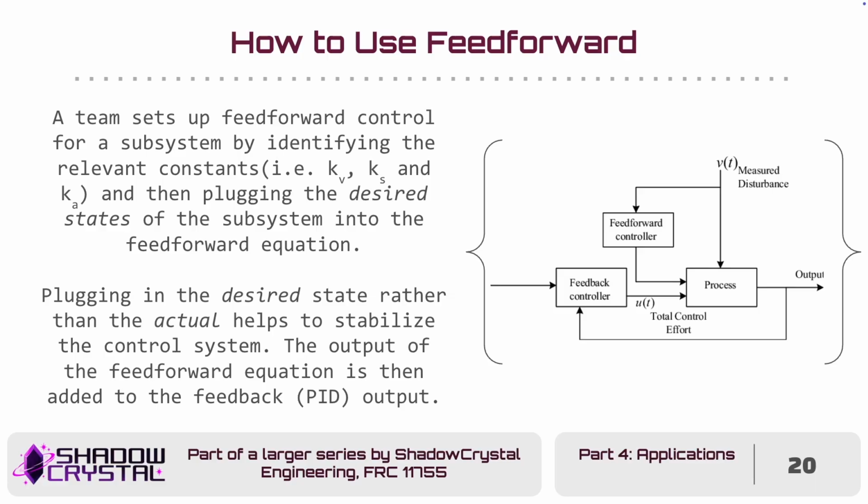Some might wonder, why don't you plug in your actual state? Because you're trying to counteract a certain force, why don't you counteract it as it is right now? The reason for that is that it helps to keep the system stable. See, if your Kv that you estimate is actually higher than it is in reality, then what you'll find is, if you apply it for a certain velocity, you're going to have more voltage than you need to counteract back EMF at that speed. So your motor is going to accelerate.